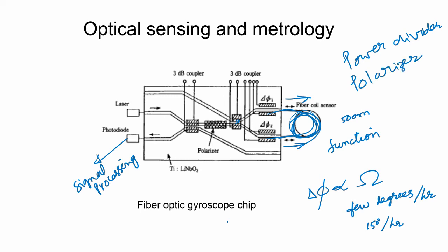You can assume that there is a waveguide, and on top of it a material which is very sensitive to the direction of the electric field of the light, and also a phase modulator here. In a typical interferometric application, the output light of the interferometer, I output, is in terms of cos square of delta phi by 2.